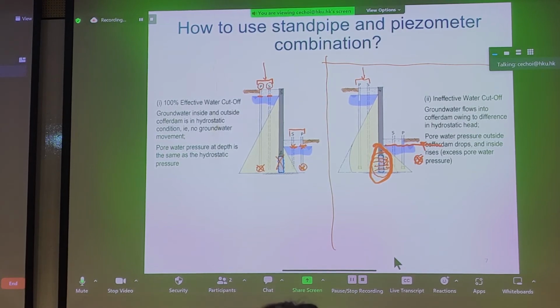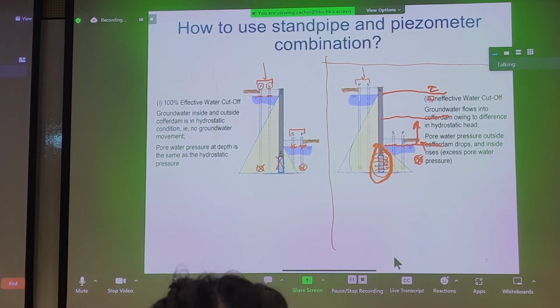And if you did not have a nice dewatering well here, suppressing this groundwater table here, let's say we turn off a pump, we would likely see the rise of this groundwater table until it reaches hydrostatic conditions with that on the active side. But let's say we have a pump that's running inside the excavation, it's keeping the excavation dry and the workers inside the excavation safe.